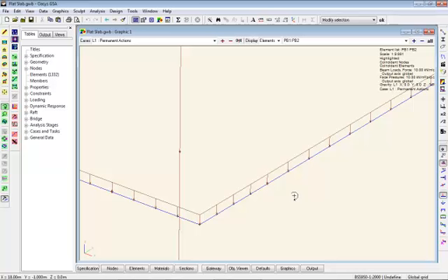So what they'll essentially do is they'll take this line load and apply it onto the slab without affecting the slab stiffness. And there are tools for that, for selecting nodes and then adding in a string of elements, or drawing one long element and use the split command to split it at the existing nodes on the mesh.